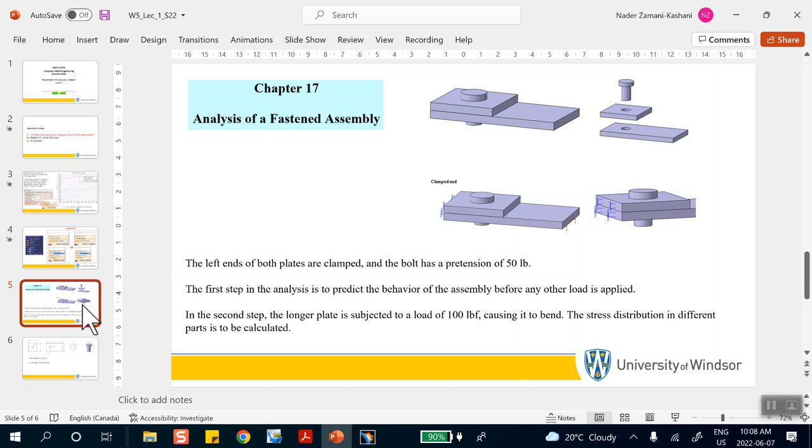But you don't model these bolts, because imagine that it's so small and tiny. If you wanted to model this, you'd have tiny little elements, of the order of maybe 1/10 of a millimeter, and then that has to connect with something here, which is probably shell. The surface of this is shell, etc. But the point is that you don't always model bolts. I want to show you what happens if you did want to model it. Maybe you are in the business of designing the bolt itself.